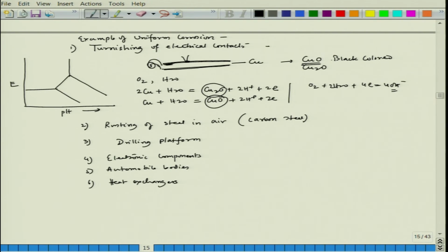Okay. In some cases, the water in the heat exchanger can contain a lot of debris or deposits, calcium carbonate deposits that might choke the pipe, and that debris can also lead to erosion corrosion. So, there are other effects also, but mostly it is uniform corrosion.